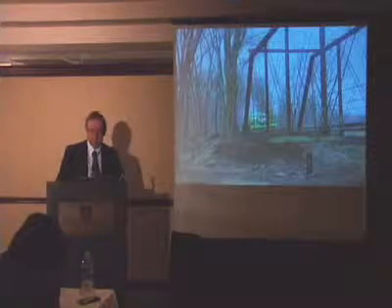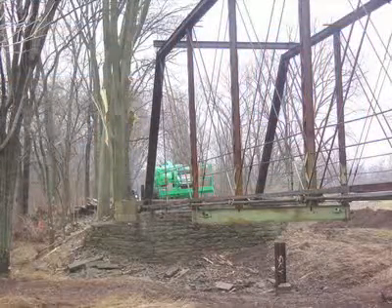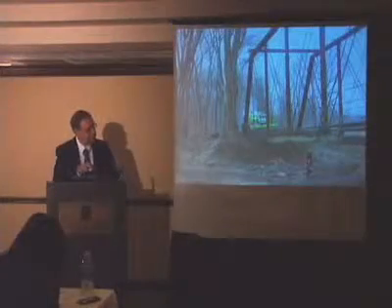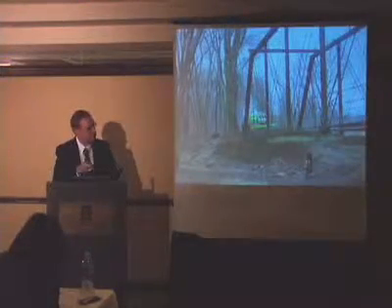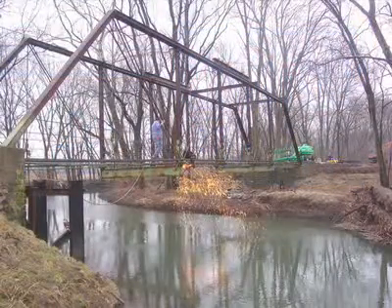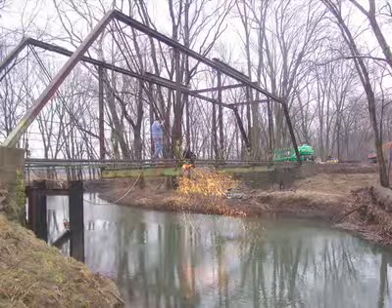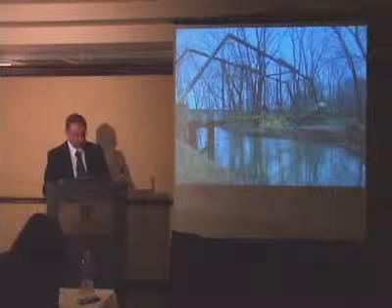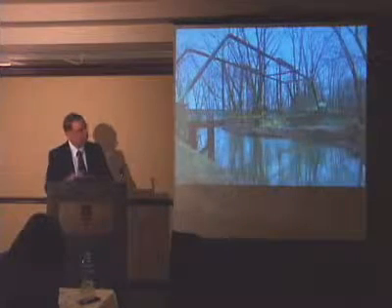Of course, the old bridge had some things that had to be replaced. So to take it down, there was a temporary piling driven to stabilize the trusses while everything was being removed. There were temporary lifting beams added to the top, temporary bracing, and the U-bars holding the floor beams all had to be replaced. So the day that it was removed, they were just simply cut out, allowed to drop. They had a cable on them, they just pulled them out of the water.